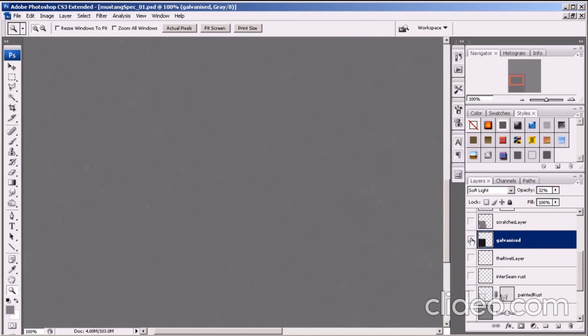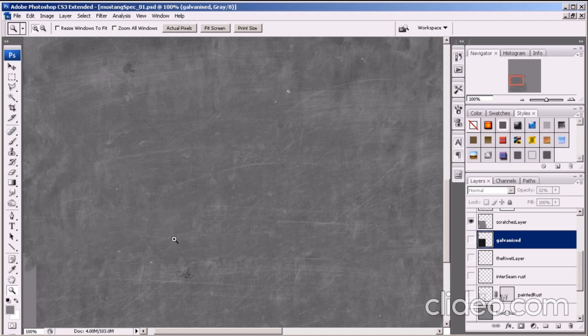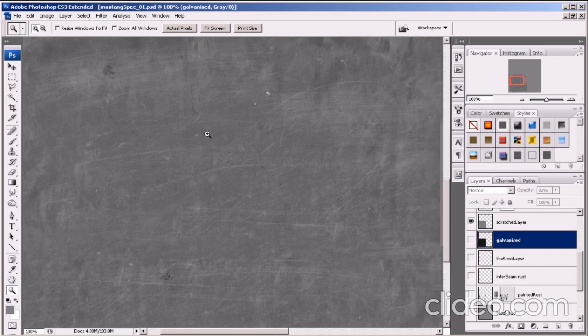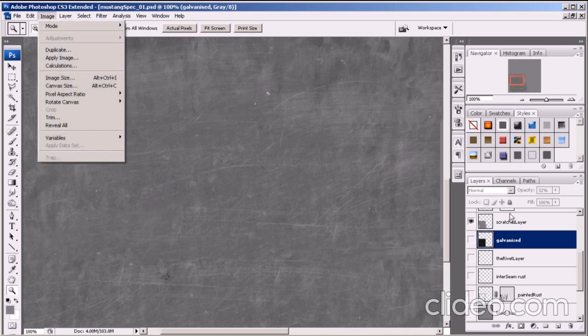Okay. The scratches layer is going to be one of the most important, and it's really down to you to decide whether, if the surface is scratched, is it going to be shinier underneath, or is it going to have more of a matte appearance underneath. I think personally we'll leave it so that wherever there's a scratch it's going to be shinier and have more specularity, but this surface here is far too light. It's still going to be very shiny. Right, so I'm going to use the brightness and contrast for this.